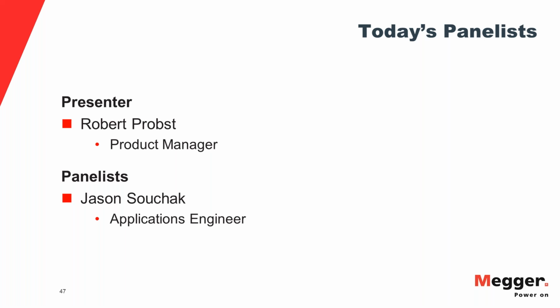All right, the next question is, when the dielectric starts developing water trees, is there some type of discharge that could be detected? Has there ever been a signature recognized that would show damage to the dielectric? The water trees don't exhibit any discharges. The tan delta test is there to detect the presence of water trees, and what they're doing is degrading the quality of the insulation and allowing more resistive current to flow through the insulation material. So we can detect the presence of water trees in that manner by measuring the resistive current and the tan delta test. But there's no partial discharge test.